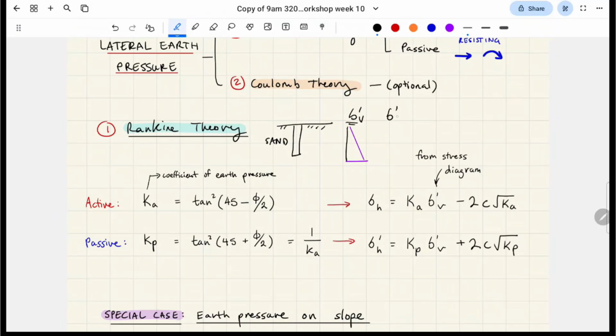When we are dealing with the horizontal graph, it's going to sit side by side with the vertical effective stress graph, except I'm going to draw the arrows in, because it represents the direction of horizontal stress. For the vertical one, I wouldn't recommend drawing the arrows because it would be misleading, but the horizontal distribution will correspond to the pressure acting on, in our case, our retaining wall.